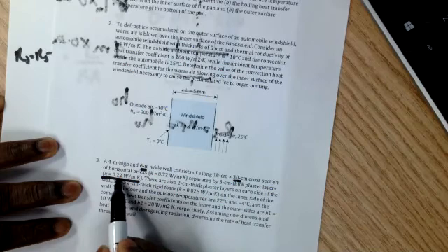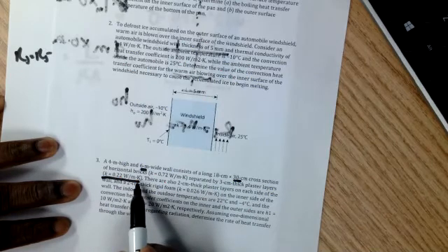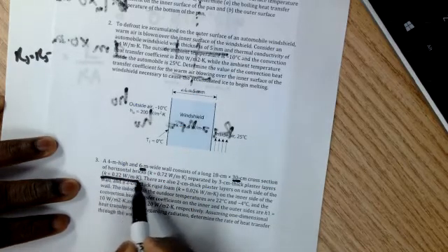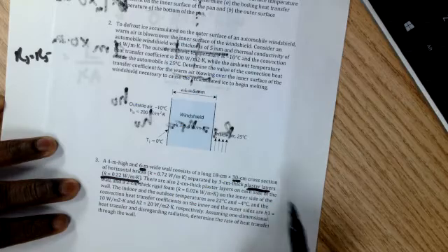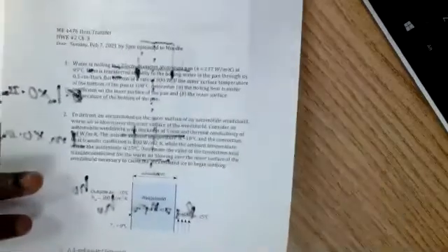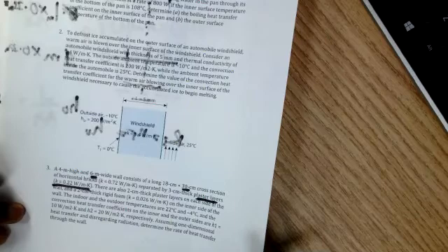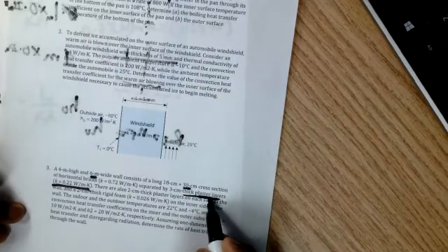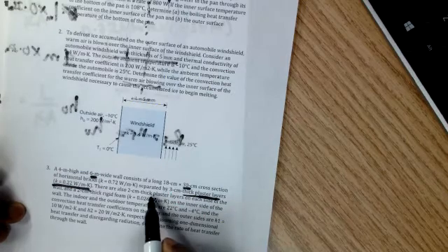So if you aren't given K for the material, then you have to assume that the same amount of thermal resistance is coming from the material closest to it. But we have a K for the plaster layers. Okay. So it means that, and also the length of each plaster layer is 3.3 cm thick. So each one is 1.5. The ones on the sides are 2 cm thick.